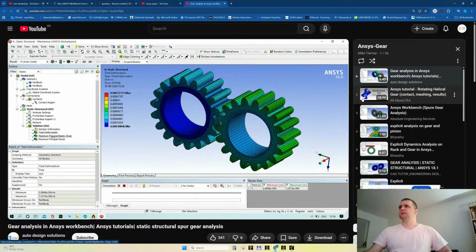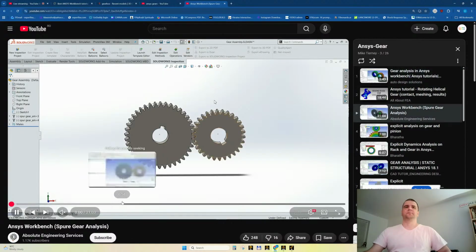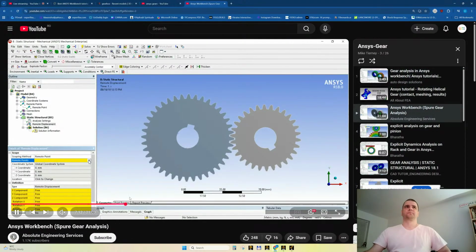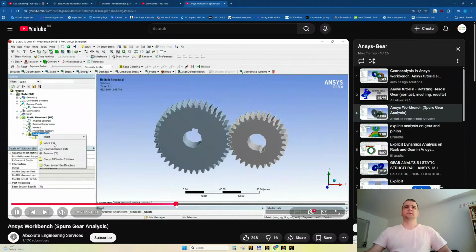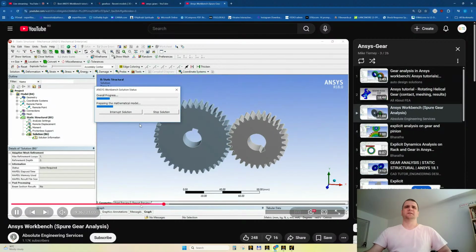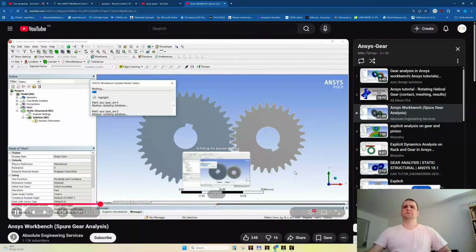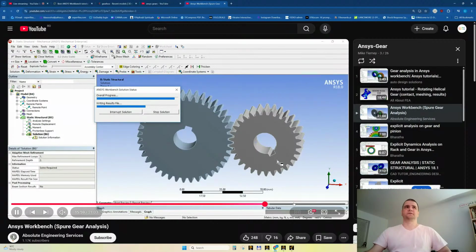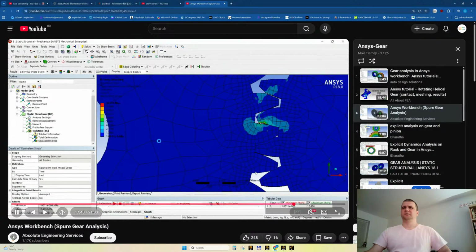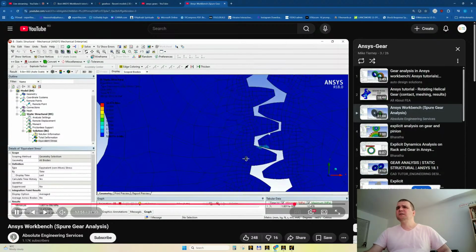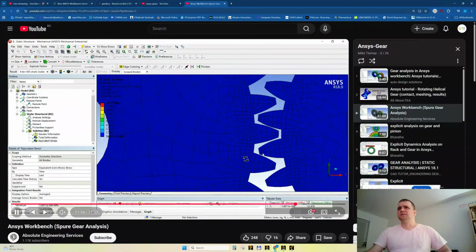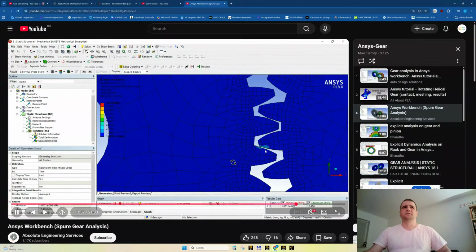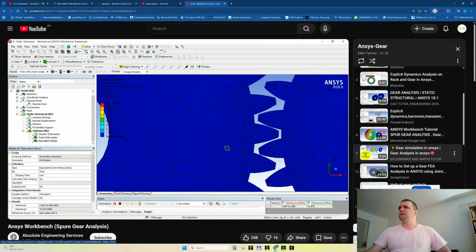I don't care about the partial portions of the gears. Let's see here. Remote point. Oh my god. No modification of contacts. So I predict bonded contacts. What is this? Yes, so it's, of course, bonded contact or no separation. The common mistake.